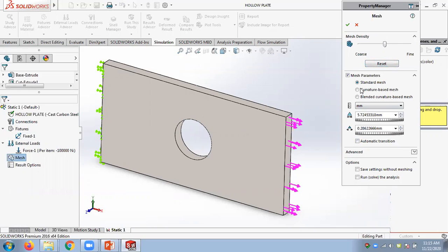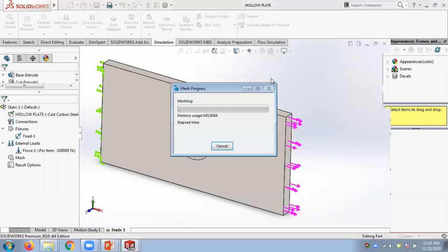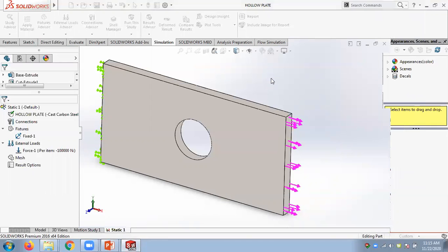We will start with this basic coarse level detail mesh at 11.1. So this element is now very big, 11.1. If you want, you can type your element size here, and element size is measured in millimeters. If I press OK now in the coarse level detail, it will put a mesh.